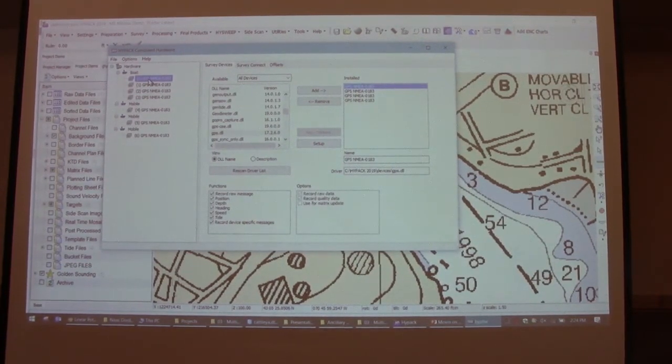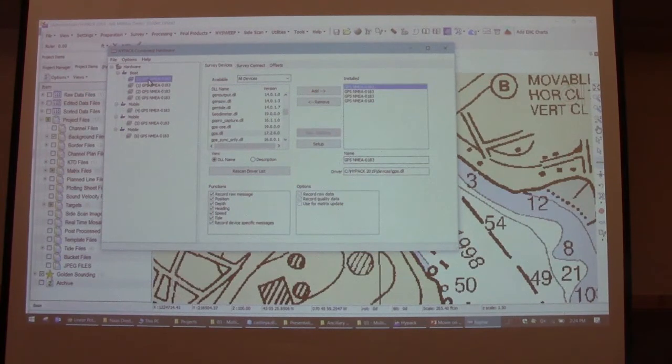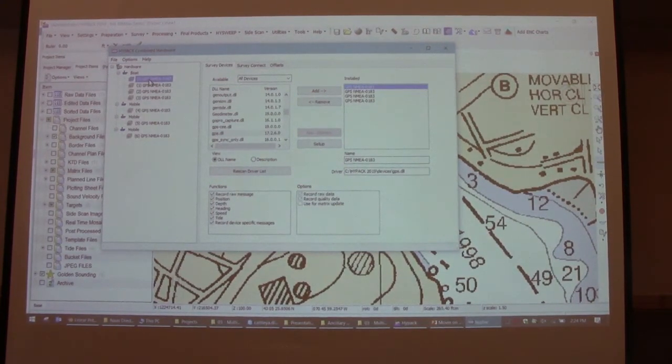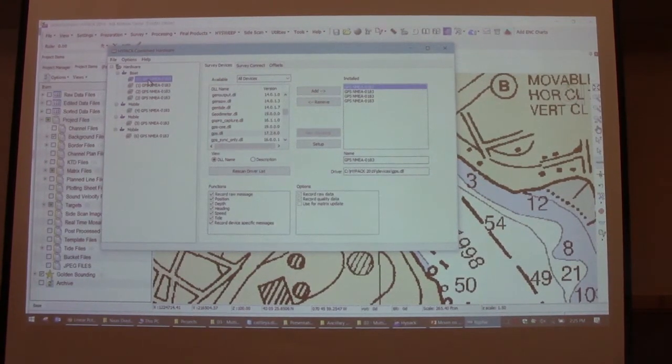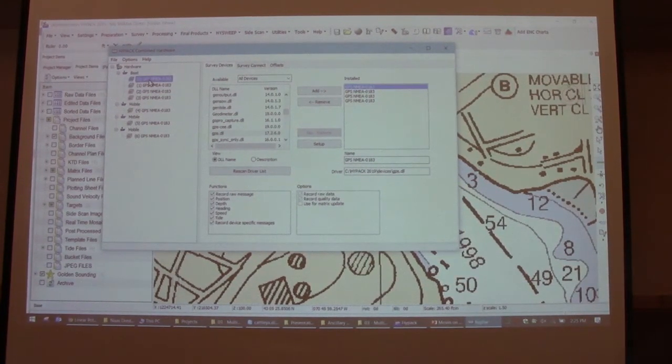I've never been able to do that. Really? That's why I thought you must have to set up. Yeah, because remember that RTK water surface elevation isn't tied to your depths. It's only a correction for depth. So depth anywhere in HYPACK is a raw depth, and then the corrections get added later to give you a corrected depth. If you start at raw depth and you add tide and you add draft and you add pitch and roll, you get to corrected depth. So that would just be a corrector.